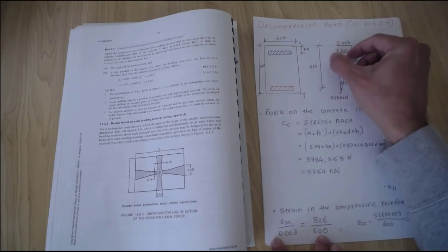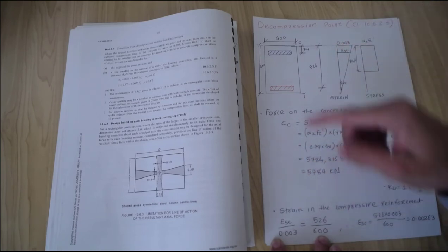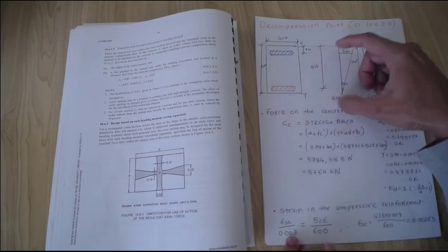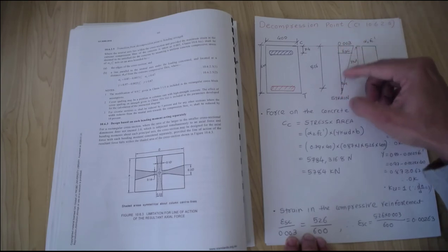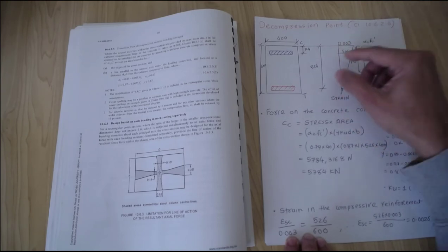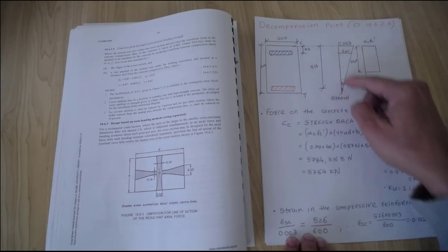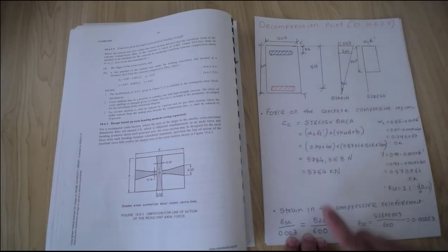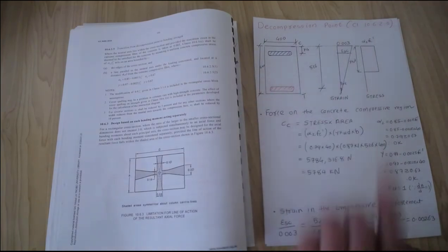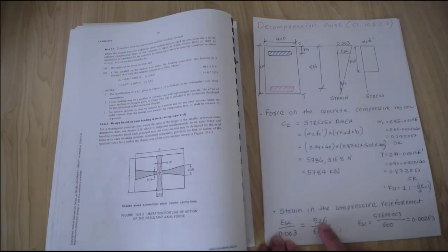It's a similar triangle, so the horizontal distance ratio equals the vertical distance ratio. So the strain in the compressive steel is 526 times 0.003 over 600, which gives me